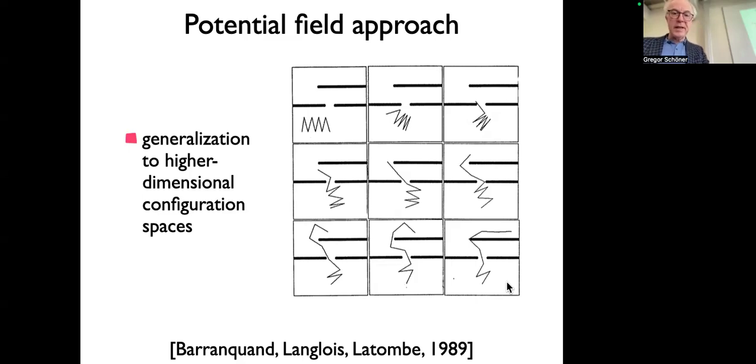Now, I should perhaps say that initially when Khatib developed that, it really played on properties of robot arms. And I'll come back to that a little bit in the second part of the course when we talk about arm kinematics. And there was essentially this notion that you can tie the dynamics of the arm, right? When arms move, they have inertial coupling and interaction torques and things like that, that you can tie that to this approach, and that you can express constraints about the dynamics of the arm in these terms.